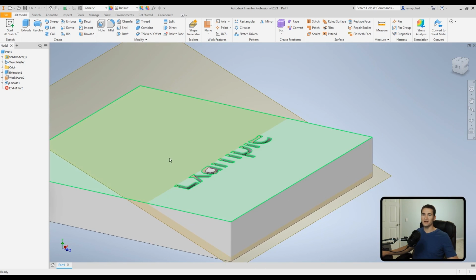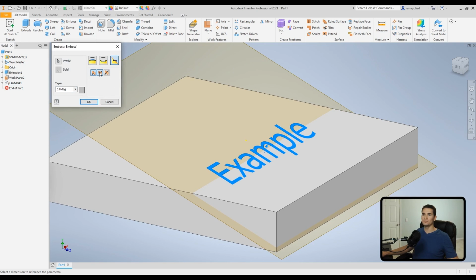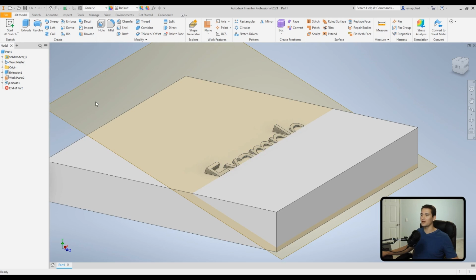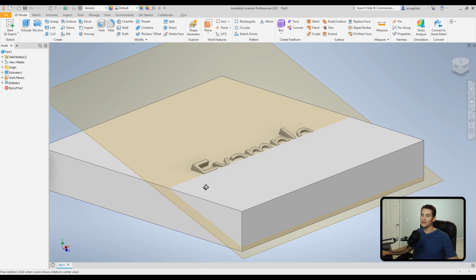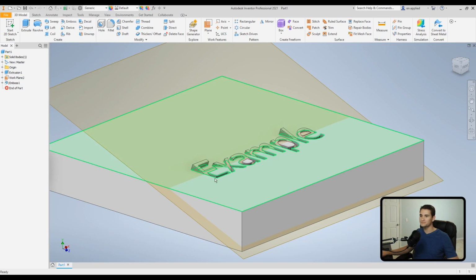Now, we'll just go back to the emboss function itself. Let's flip this direction. We'll click this middle button first. We'll click OK. And the arrow was pointing down, and you'll notice it does the exact opposite. It goes from the plane down into the body, and it creates 3D geometry in this space. So we have these raised lettering on angle here. So let's go back into Emboss, and let's do this double arrow version or the symmetric version of it and click OK.